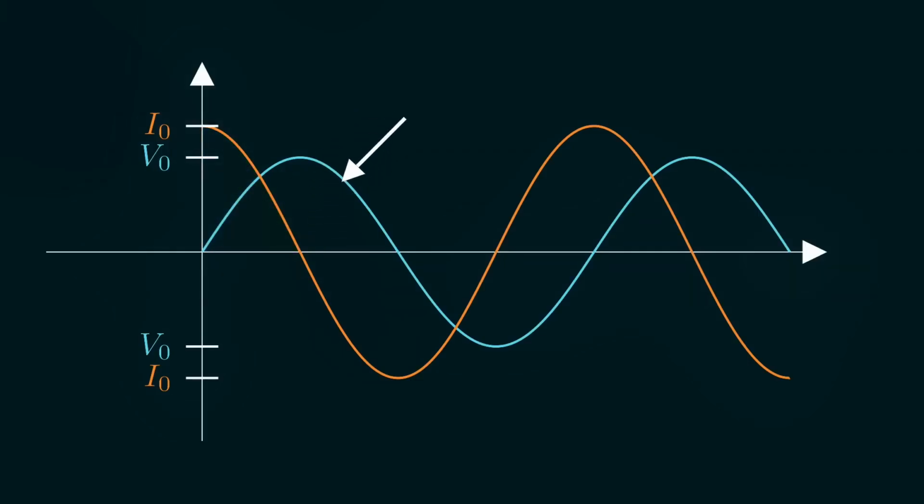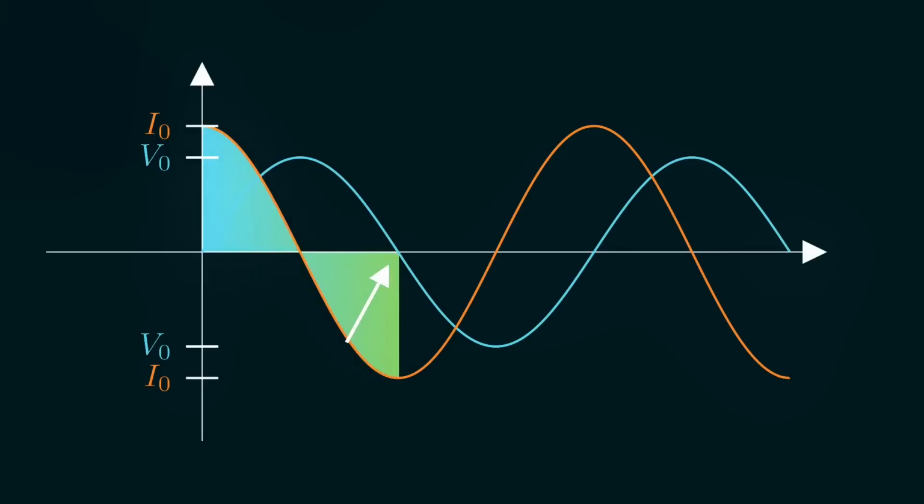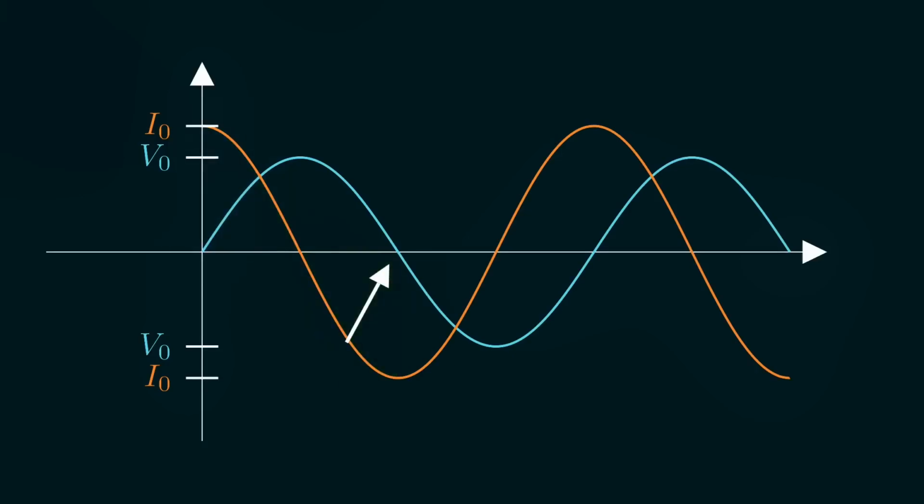Now when you start decreasing the voltage, the capacitor has excess charge on it. So to get rid of it, it's going to start discharging by sending current in the opposite direction, which is where we get the negative current from. And it'll keep discharging more and more until the voltage reaches 0. At this point, the areas under the curves cancel, which means that there's no charge on the capacitor right now. So when the voltage starts going negative, it's going to act like a wire again, quickly drawing lots of current, except now it's in the opposite direction. And now we have the same cycle repeating, but for negative charge and negative current.